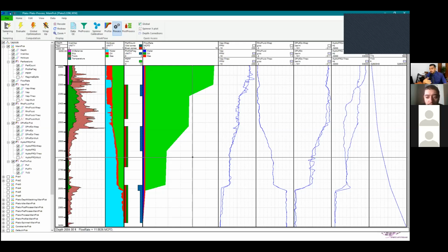However, if all of these perforations are watered out, you need to look for other zones that you have not perforated that contain oil. And if all of these perforations are watered out and there are no other layers bearing oil, I'm afraid you cannot do much about that. Either you produce the well at its capacity, maybe with 70 or 80% water cut, and you just have to deal with that. Okay, thank you very much. You're welcome. So let's say bye-bye to the field.